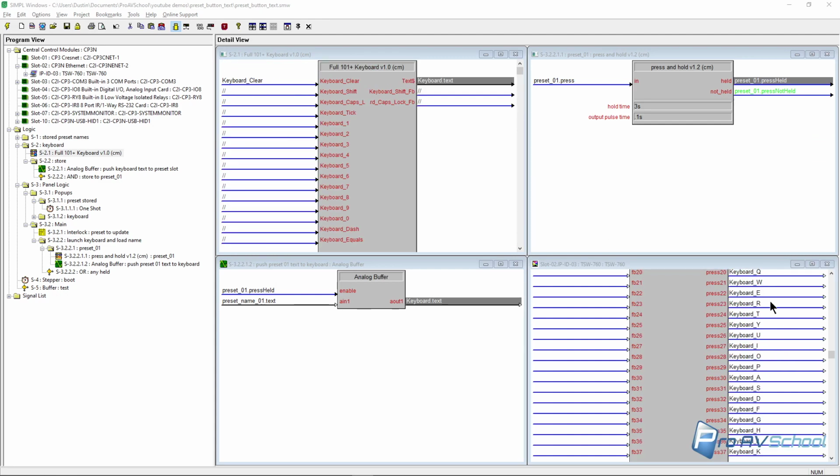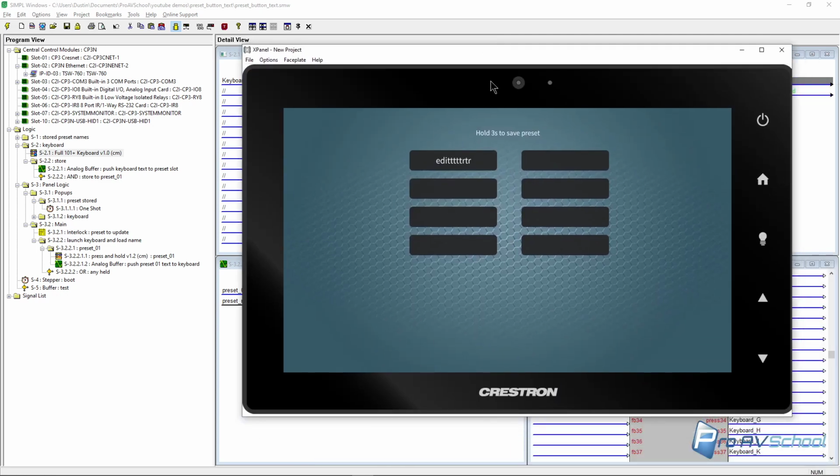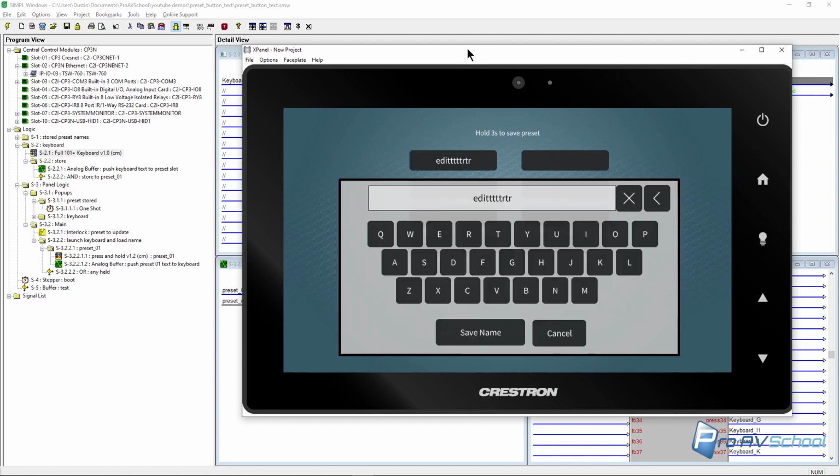So we've basically got just the keys, and I didn't put numbers and stuff. You can spend much more time. You could have also used a keyboard input type in Vision Tools Pro E. I don't usually like using that just because I can't control how it looks. It's kind of rendered by the underlying operating system of the touch panel, and also, importantly, I can't simulate it on an X panel, and I like to be able to simulate things because I don't keep a lot of hardware in my office.